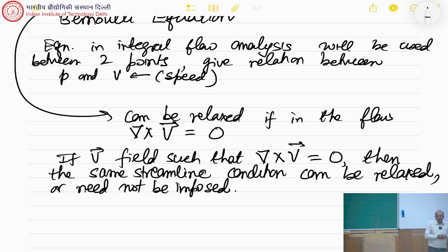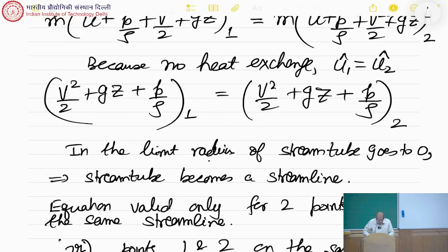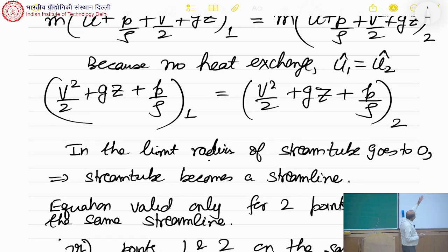And right now it is difficult for me to explain it, but the way we can look at it is, if I look at the differential form of the velocity equation, then I can get an energy form from there also. And when I look at the energy form from there, then I get this expression. And in some sense, what you can look at is that this quantity P by rho plus V square by 2 plus gz, let's call this Bernoulli's constant, B.